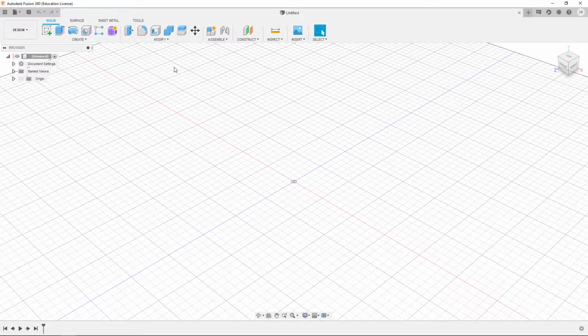This video is going to focus on using the Revolve tool. We've seen different tools that let us make 3D shapes, particularly extrusion, but the Revolve tool allows us to take a 2D sketch and rotate it around an axis, as opposed to pulling it perpendicular or in parallel with the plane that it's drawn on. This allows us to make more advanced shapes. We could make a profile view of something and then spin it either all the way around a circle or partially, and we can get some interesting objects that way. So let's try an example.